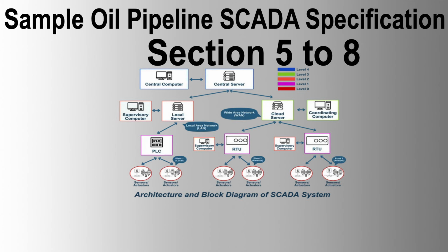6.4 Ventilation. Ventilation requirements shall be arranged to avoid the creation of local hotspots. Forced ventilation systems shall not be fitted unless agreed by the owner. If supplied, forced ventilation systems shall consist of twin paralleled systems, each rated at 100% duty, fed from a UPS via dedicated fuses and circuit breakers.